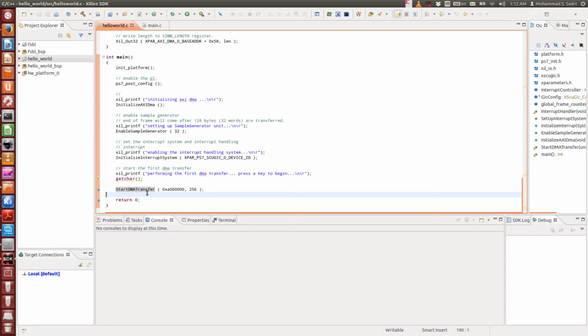Actually, this is practically not needed. I have finished the main function completely normally. After starting the DMA transfer, I say return 0, and then I finish everything. And this operates correctly because after this code gets compiled, that infinite spin loop is added automatically to the end of your program.